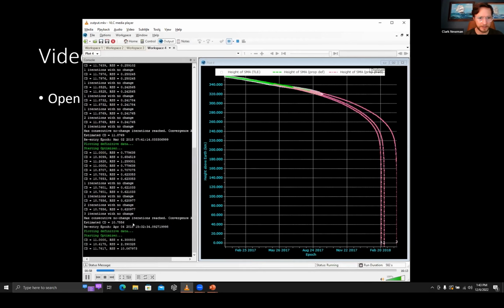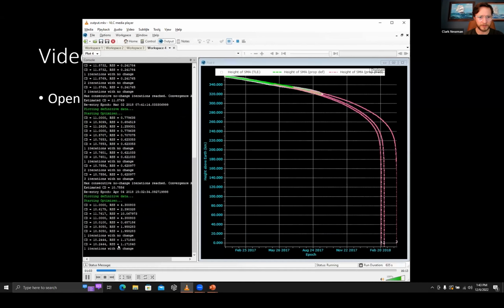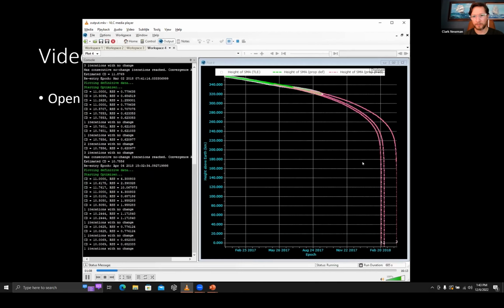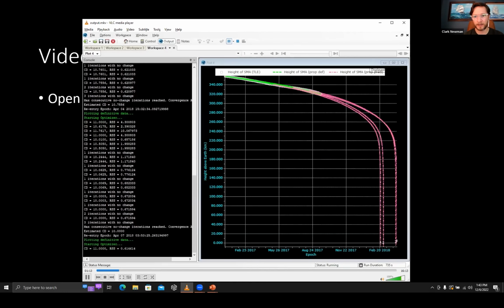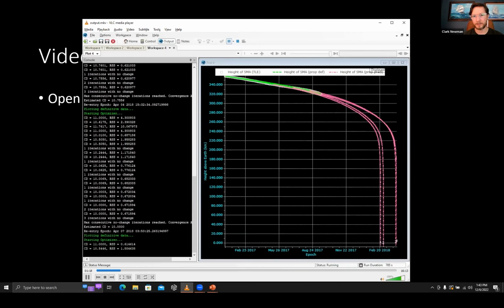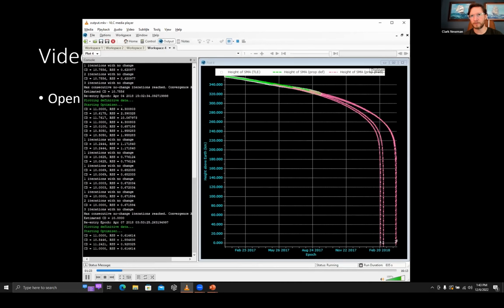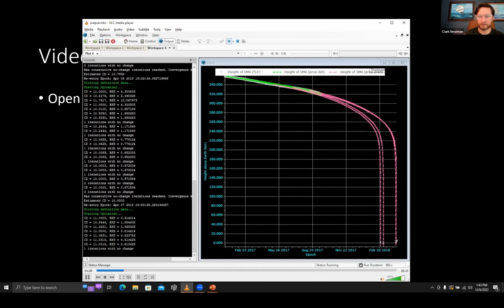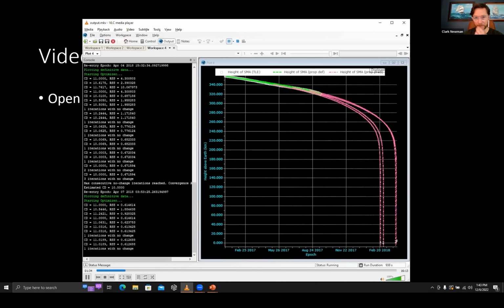And this time it's actually really close to the actual reentry epoch of, I want to say, April 18th or April 12th. So we're running it again on the last 300 TLEs, and then a fifth time using the entire set. What this aims to demonstrate is the transient nature of training any kind of system to estimate your drag coefficient on a variable atmosphere. There's a lot of temporal changes to consider.